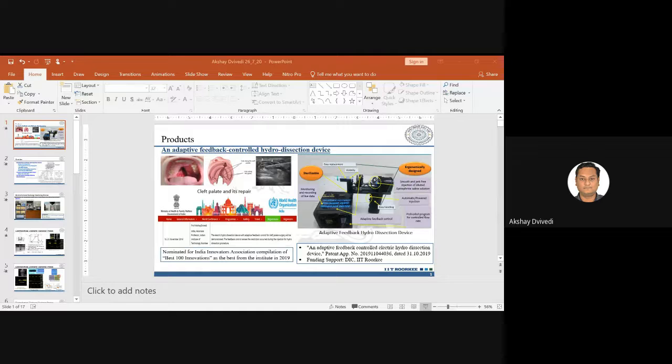Now, here, what was identified is, if you provide the electrolyte drop by drop, is it possible that you can quantify the amount of electrolyte that evaporates during, let's say, one spark? And then you should supply that same quantity of electrolyte. If you can do that, that is going to provide far better consistency.